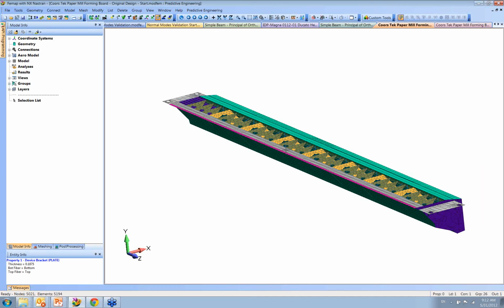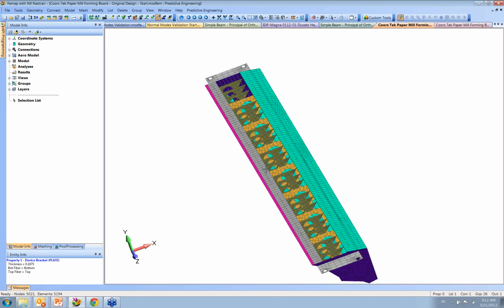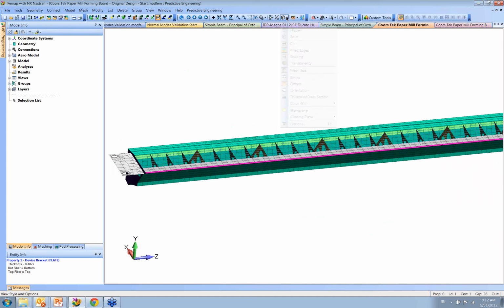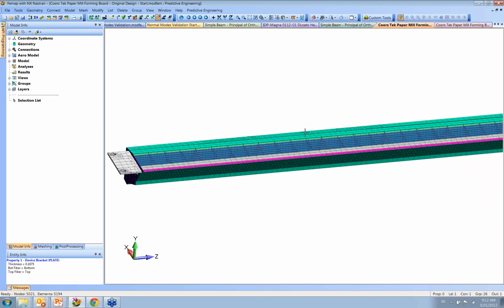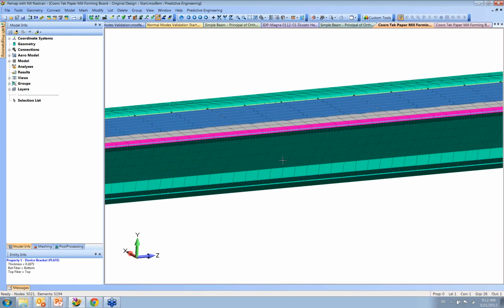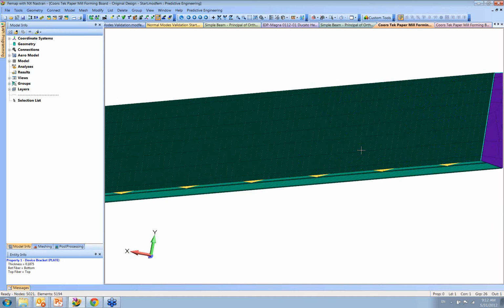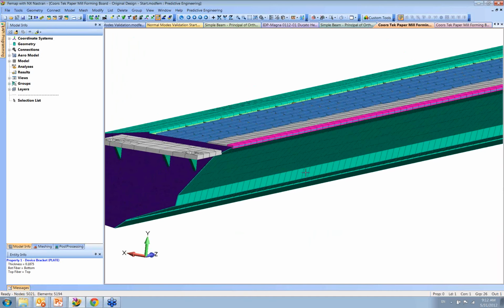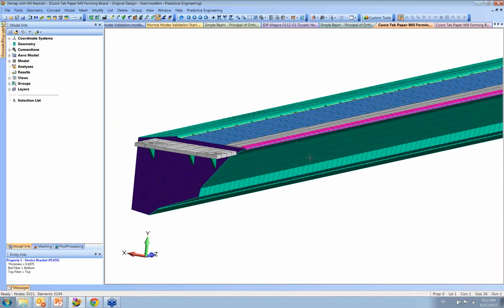And it's all stainless steel, a big structure, really expensive. And we just beat on this till it just went on and on and on. And it was tricky. It's long, and you have this forming board. We were trying to figure out, and stainless steel is expensive, big, and it's a classic thing. Your frequency is the square root of stiffness over mass. Anytime we tried to add thickness here, it added so much mass that the frequency just went down. And I'll show you what I mean.